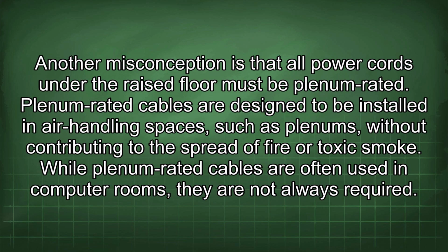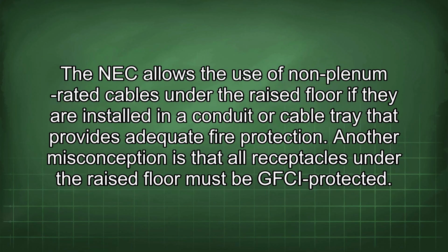Another misconception is that all power cords under the raised floor must be plenum rated. Plenum rated cables are designed to be installed in air handling spaces, such as plenums, without contributing to the spread of fire or toxic smoke. While plenum rated cables are often used in computer rooms, they are not always required. The NEC allows the use of non-plenum rated cables under the raised floor if they are installed in a conduit or cable tray that provides adequate fire protection.